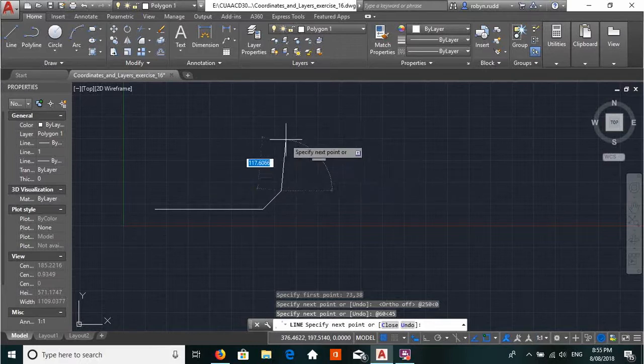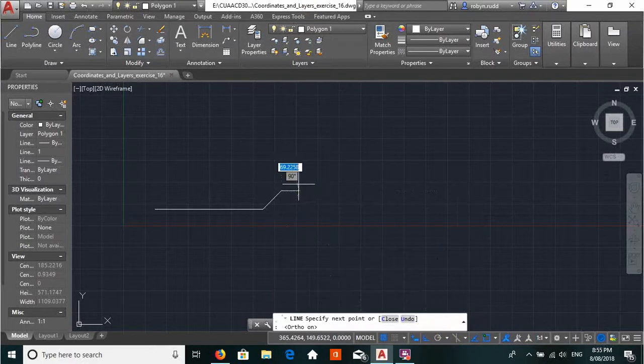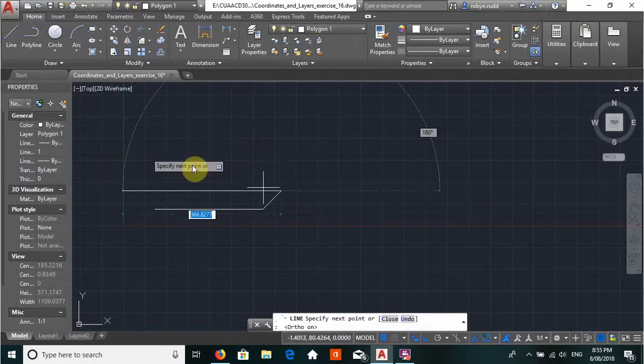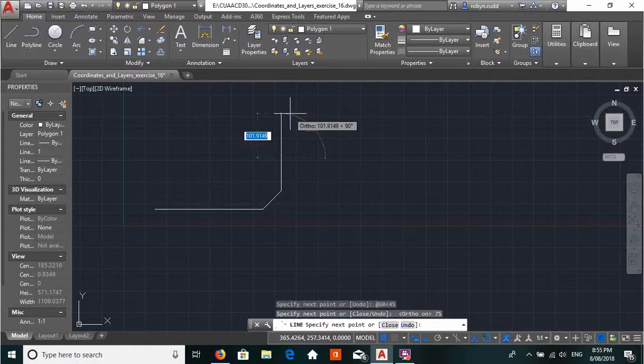And then you can either go up by putting on your ortho, because that only allows you to go in 45-degree angles. Okay, so I just push my cursor upwards, and I can just type in, blue, which is my hairline there, just saying 75. Enter. Okay. All right. So did everyone see that?